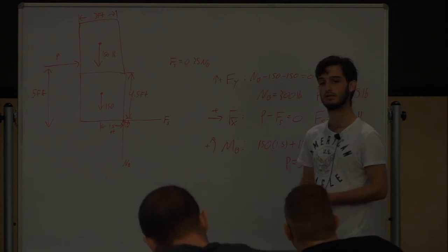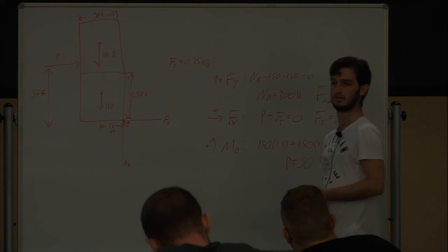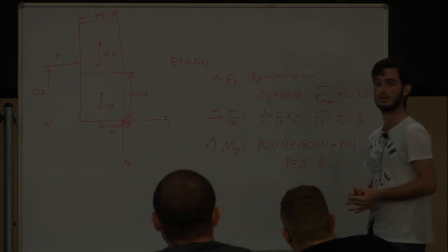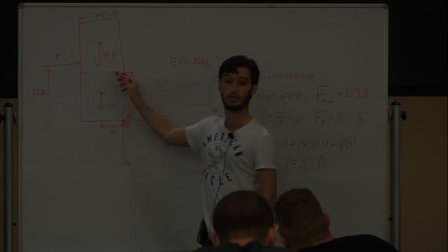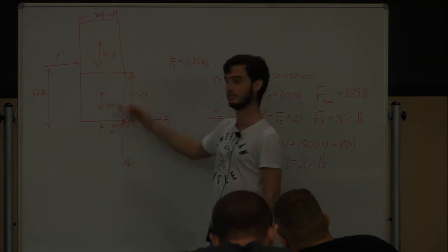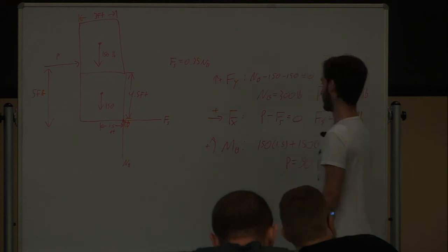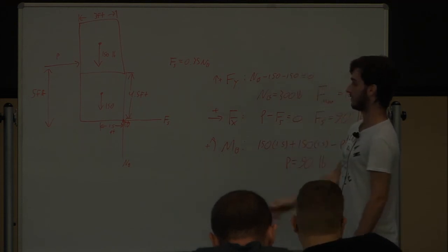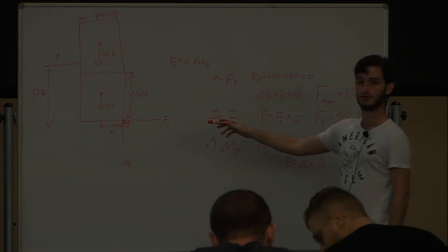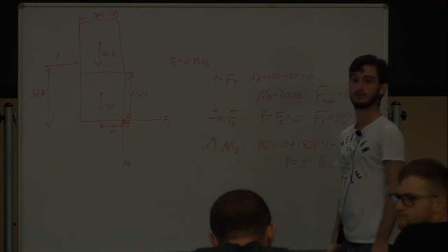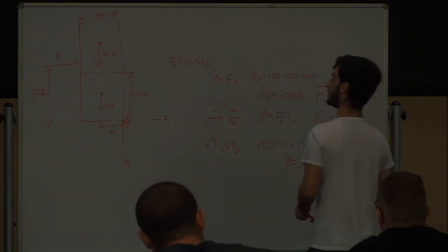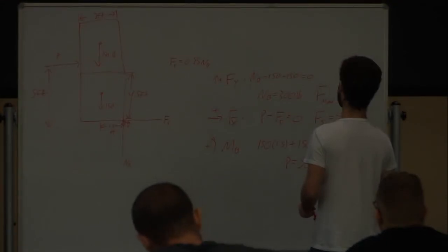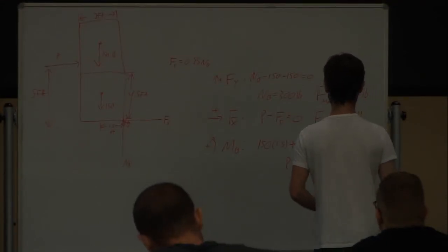Right. Well, let me ask you. If my forces are still here, this object can still tip, right? Box can move alone. So, as long as my forces are there, it can tip. It's not going to slip because 90 is less than 105. So our minimum force so far right now is 90 that we need to move those boxes. So we need to draw a free body diagram for the top box.